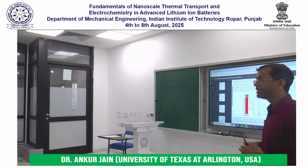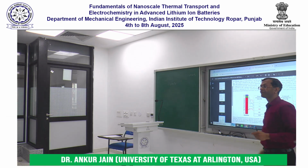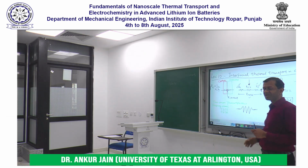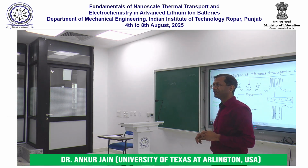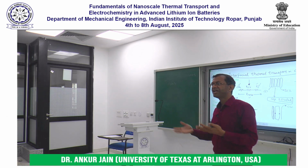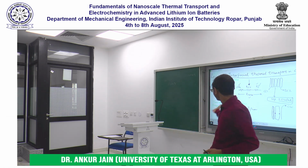right? I'm able to get a significant reduction in the total thermal resistance primarily because I identified the rate limiting step and I focused my energy on reducing the rate limiting step. If I go back to my slides, it is this biggest resistance that I must focus my energy on and not these itty bitty things, right? If I'm trying to save money and if I spend 10 rupees on chai every day and 200 rupees on cake every day, then I should be looking to reduce my cake consumption, not my chai consumption, right? That's what is happening here.